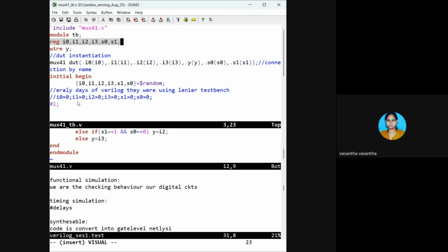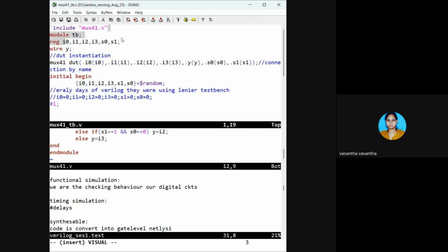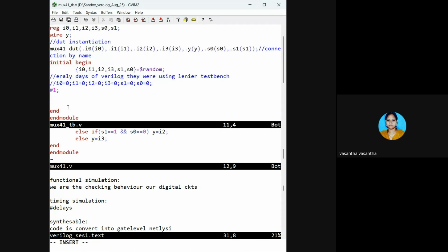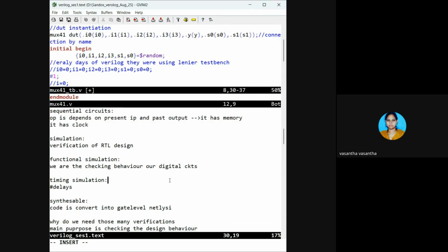Here is an example. The reg we declared. In the next unit of time, what is the possibility? You guys can tell me. I equal to 0, when manually initializing the values, it is like this. So nobody is following this kind of linear test bench as of now. Nowadays, everybody is applying dollar random. The tool will generate it. What is dollar random? I will write here.